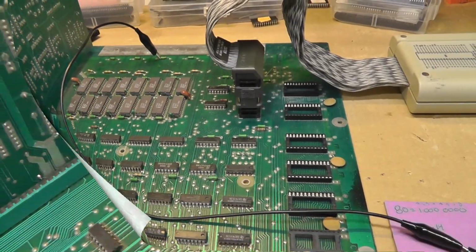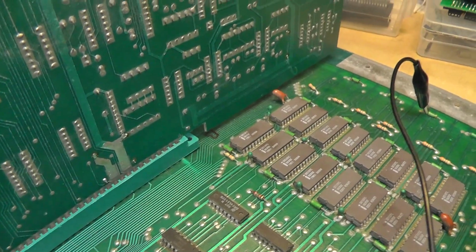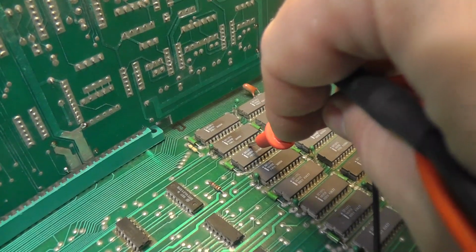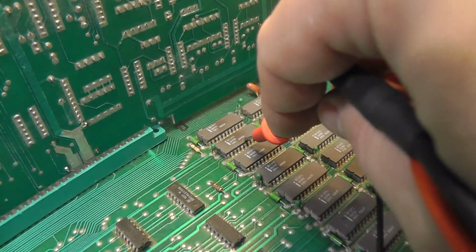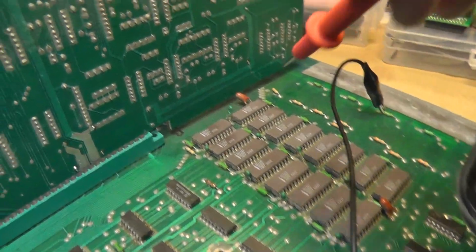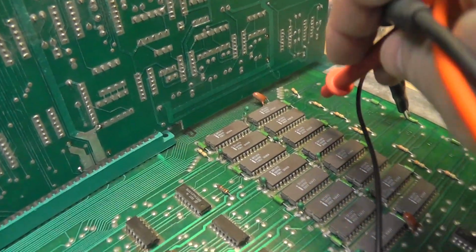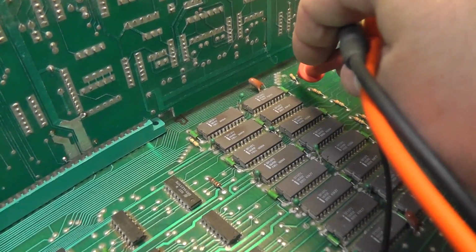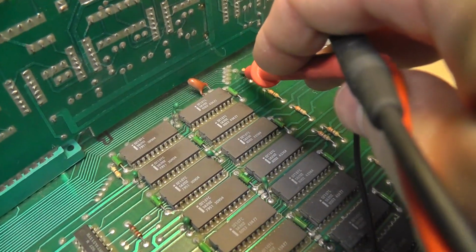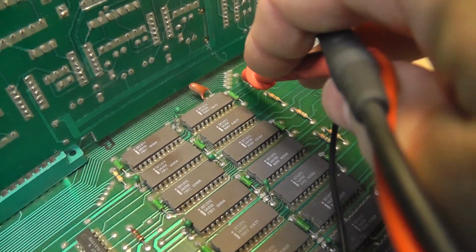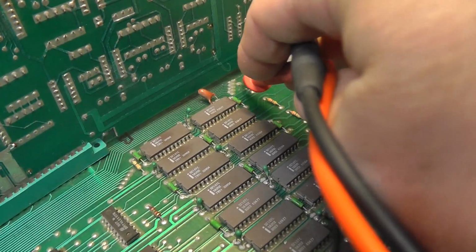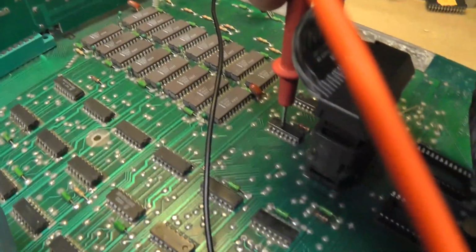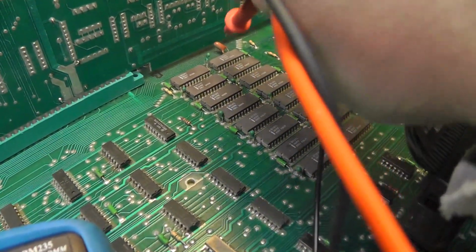Let me come back. Alright, I thought I did it more scientifically, but I guess I just came and looked at the schematic and wanted to see what the data input line, so line 6, was tied to and how it got onto the data bus. First it went to this 330 ohm resistor here, and then I looked up here and I could see this resistor is broken, is not tied. So my data line is not tied to the resistor that then goes to eventually, I guess, whatever these 8216s are. So I know that's my problem.